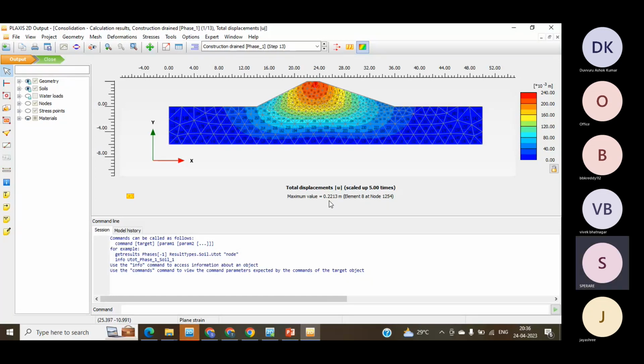when your pore pressure calculations are happening above the groundwater level, automatically, though it is a hardening soil, you're weakening the soil because it has relief to pass these pore pressures inside. And because of these pore pressures, the soil may not get highly compressed in nature, the molecules are not near to each other, like the crystals are not in good contact. So that's the reason you may lose the stability. And this is the best example that you have seen.